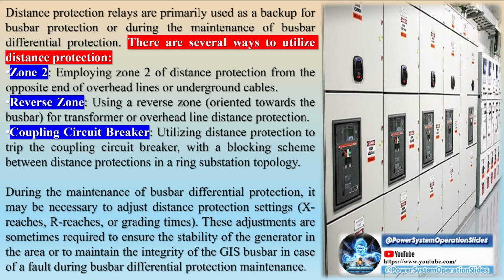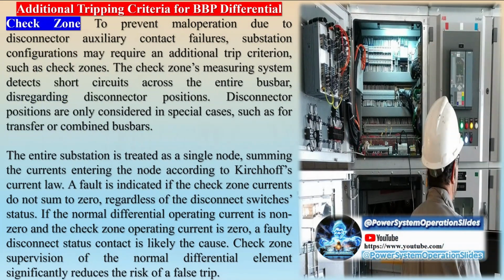Arc flash detection relays utilize this phenomenon to achieve faster response times, providing greater protection than conventional relays. Conventional current-based protection techniques can be slow in clearing arcing faults, increasing risks to personnel and equipment damage. Optical detection techniques in arc fault protection enable fast clearance of arcing faults. AFP can detect arc flash events and send a trip signal within 2 to 4 milliseconds using high-speed output contacts, or 15 milliseconds for relay contacts.